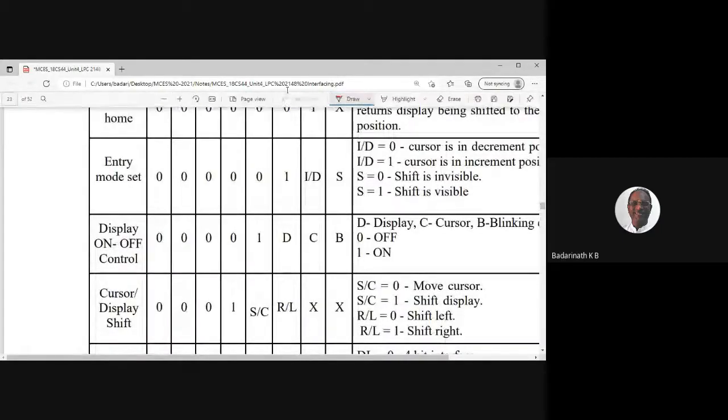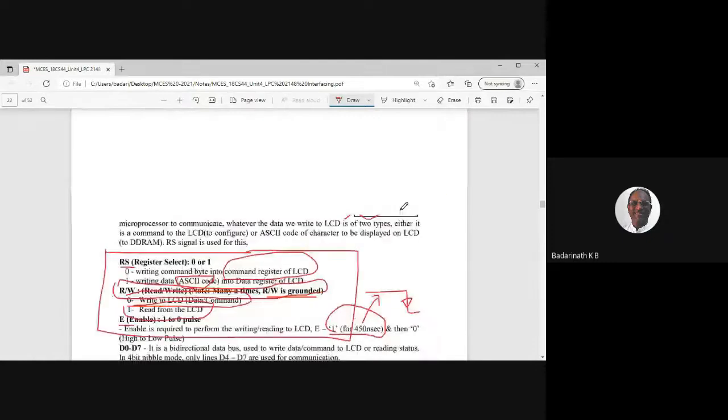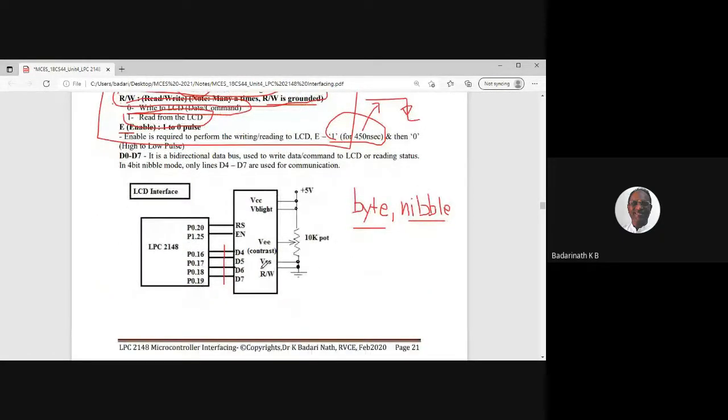So now we'll go back to here. What I've done, I have written one function. What is the name of the function? Send higher nibble. Whenever I give a byte, send higher nibble will take the upper nibble and write it exactly into this portion. I did it. Now I have the basic functions available. Now I have to develop two functions to make the LCD receive the data.